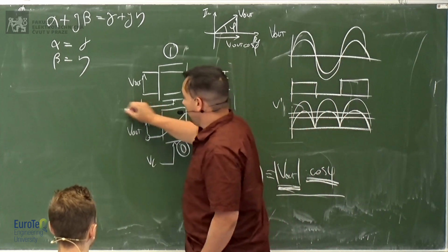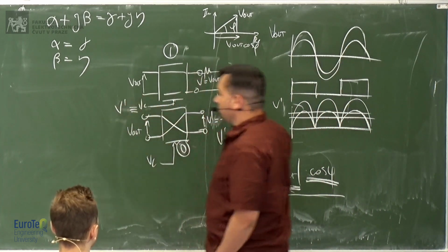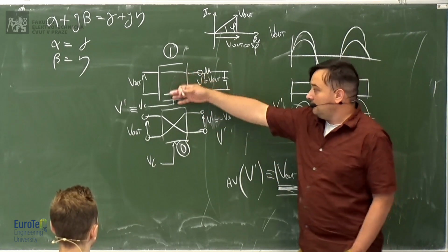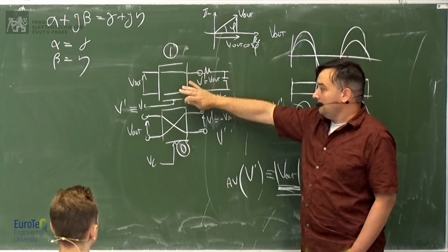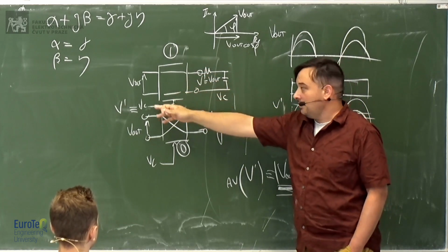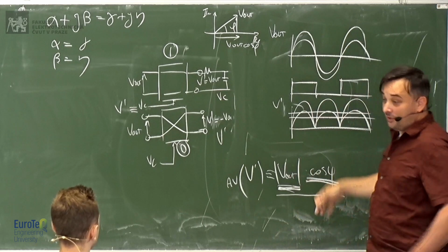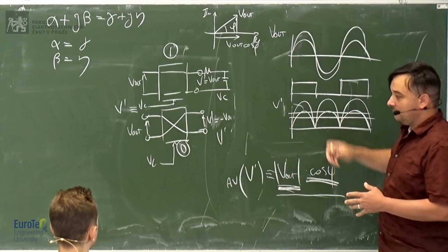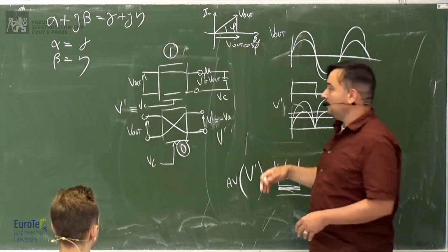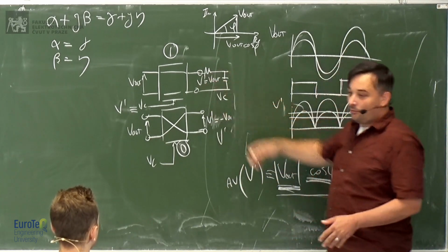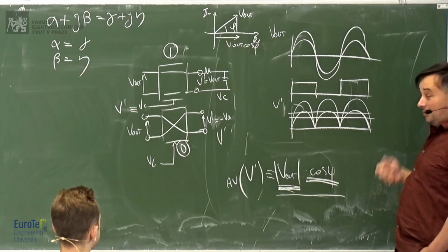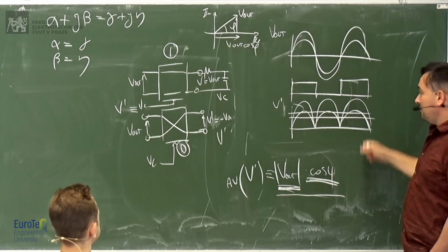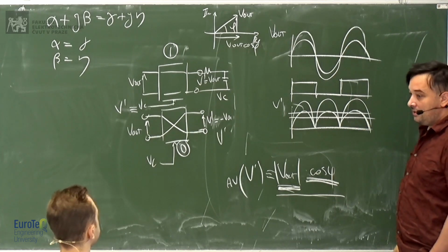V1, which gives us our control voltage, then just put the V out to this voltage to the flipper, make it flip with the same frequency of the voltage you want to measure. The input voltage of the operational amplifier, of the inverting amplifier, and then you have a low-pass filter which gives you the average value. What is the advantage of this circuit is that it selects only this frequency, okay?